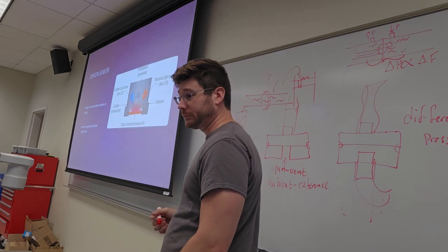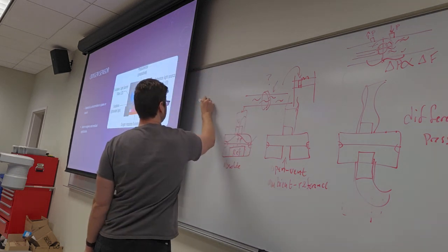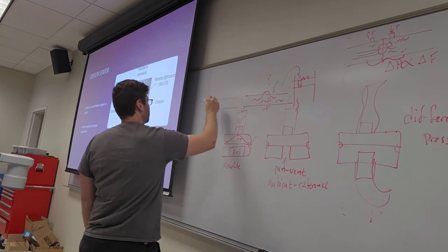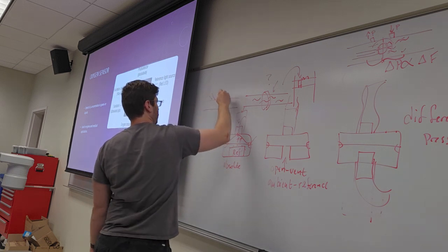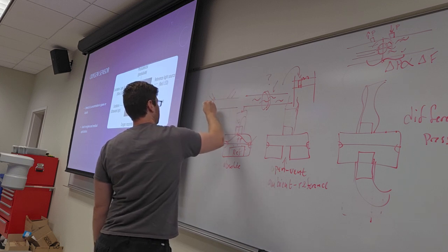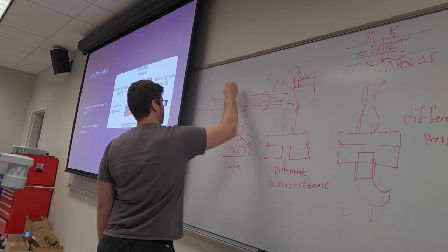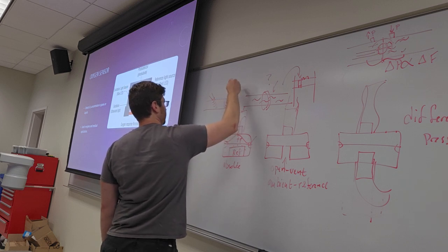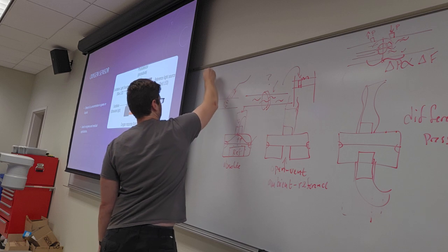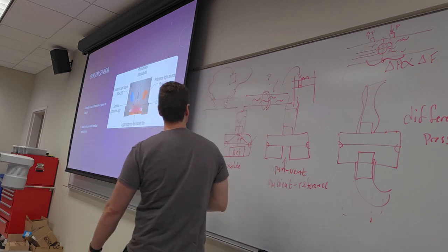There are also many others. Just one other flow sensor type, while I'm thinking about it, is ultrasonic, okay? If you have a sending head right here and a receiving head right here, okay? This is like an electric probe, this is an electric probe. Both of these plug into a PLC or a box that plugs into our PLC.